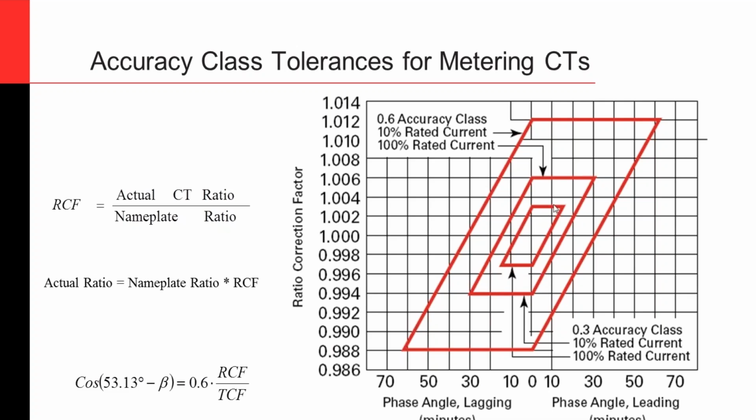And for 100% rated current, you want the response from the CT to stay within that very narrow inner parallelogram.